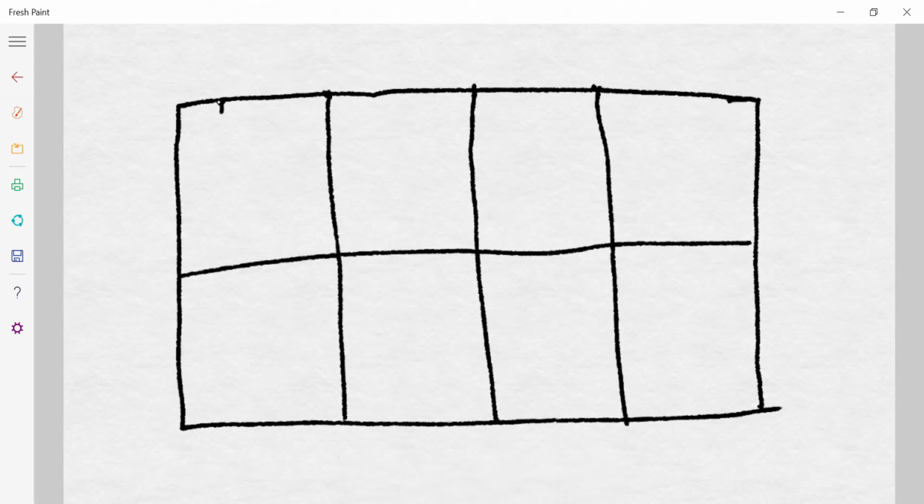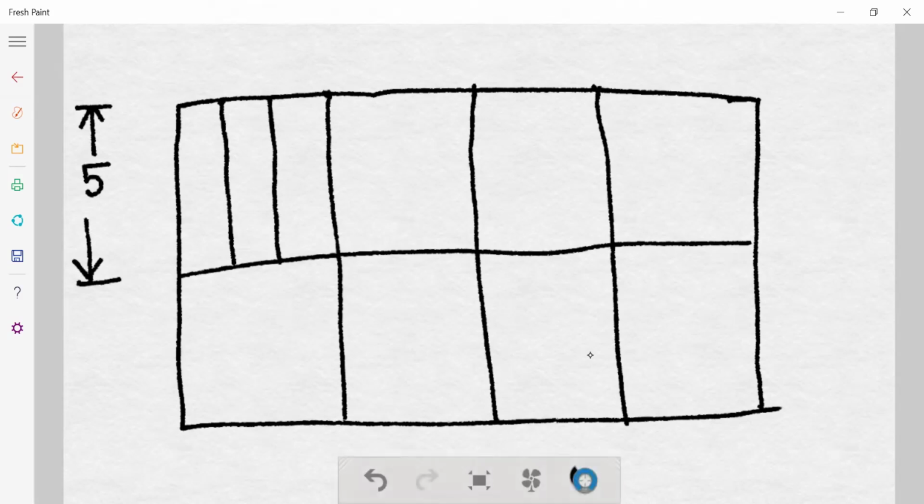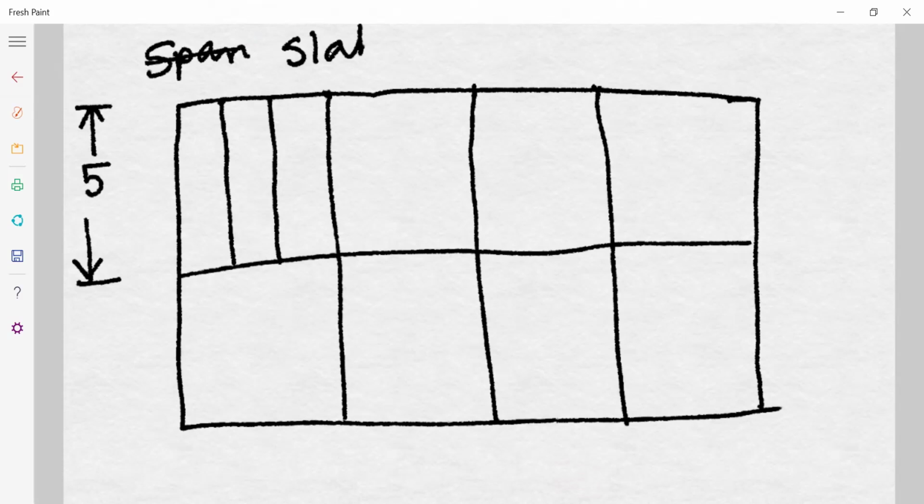So I consider these two beams secondary beams. Okay, so span of the beam will be how much? Span of the beam will be same as this one, 5 meter. Okay, span of the beam is 5 meter. So now the load goes in the beam from the slab. And what area of the slab contributes to the beam?